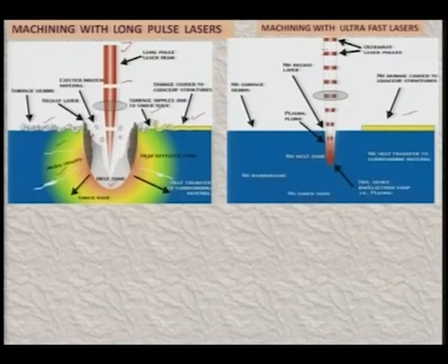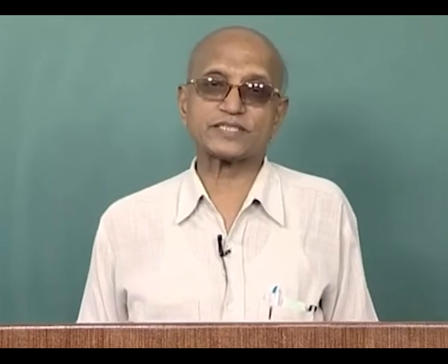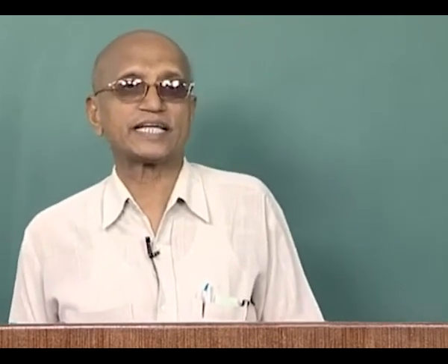So, this simply indicates that for accurate precision machining with the help of laser beam machining, one should go for ultra fast lasers or ultra short pulse lasers if economics permits, because this has to be decided based on the economics of the process, because there are certain jobs which really do not require that kind of accuracy or tolerances.